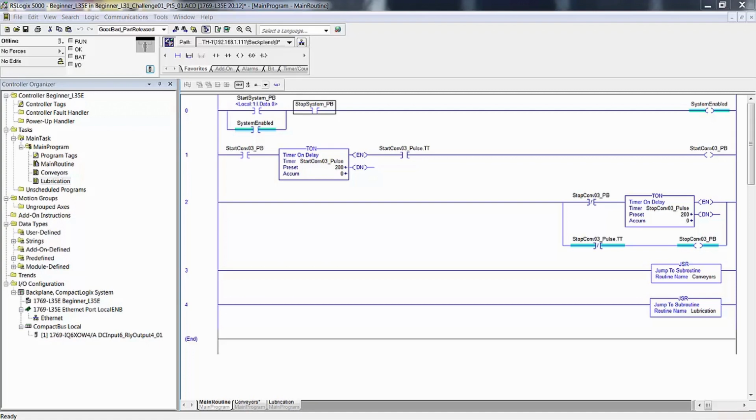The physical location of sensors is always an important criteria when writing a control program. Can't tell you how many times I was shown a diagram, I wrote the program, I got out to the field to commission the system, and the photo eyes were not where they were shown in the diagram. And that does change how you write your program. So first you see if you can adjust the photo eyes to the position that matches what you'd considered in your program. If you can't, then you have to edit your program a little bit, maybe even a lot.